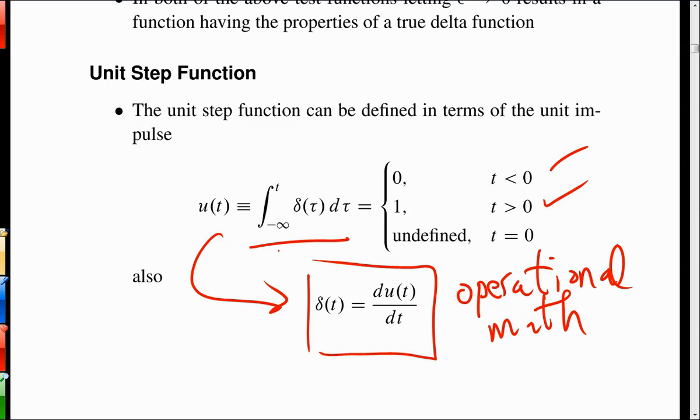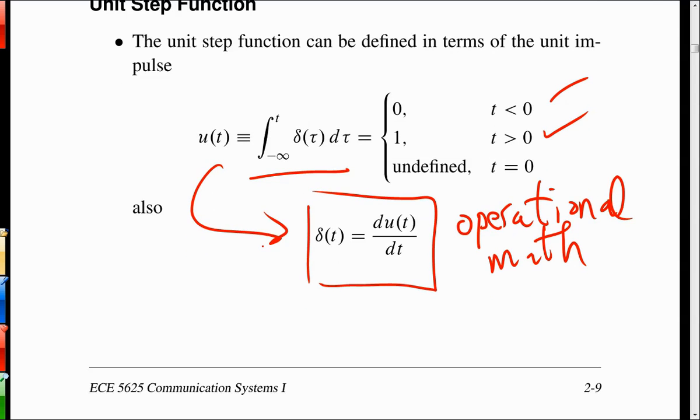You cannot make the voltage across a resistor, or anything for that matter, instantaneously jump. There's going to be some distributed resistance, capacitance, and inductance, which is going to keep it from making those instantaneous changes. So a simplified model of a step, or a more realistic model for a step function, is probably something like you would imagine measuring on the oscilloscope in the lab. It would be something that would come along and it would transition like something like that.